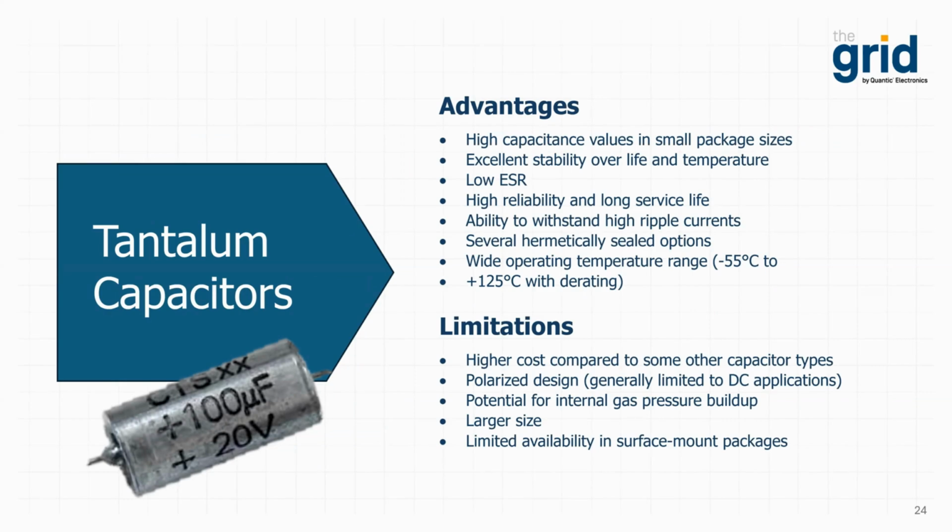They're actually very low in ESR, and they're known for their high reliability and long service life. They do have the ability to withstand high ripple currents, and they're often offered in hermetically sealed options. They do have a very wide operating temperature range, typically from -55 up to 125 degrees C.